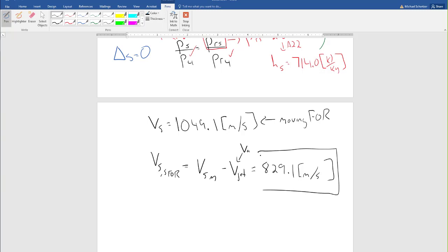The other thing that people often mess up here is that they forget that the back work ratio is 1. So people will often set the pressure at the exit of the turbine equal to the pressure at the inlet of the compressor, and that will mean that their turbine is producing a lot more power than it quote unquote should, which means you'll get a lot less velocity coming out. So if you get a velocity that you feel is really low coming out of your turbine, then that's probably the problem.